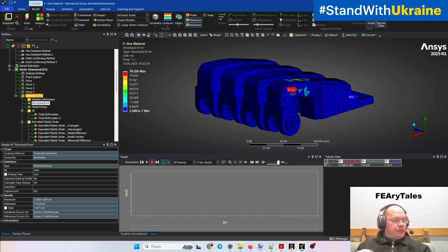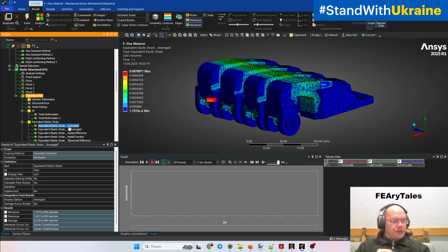Okay, so what is very important? That's the reason why, when you create a report for the finite element analysis, you not only describe the number of nodes and elements, you not only show the mesh for the whole geometry and for some important parts of the geometry, you not only say what software you use, but you also must write the options which you use when you visualize the result of your calculation. Because depending on software and on options, you can have very different types of result.